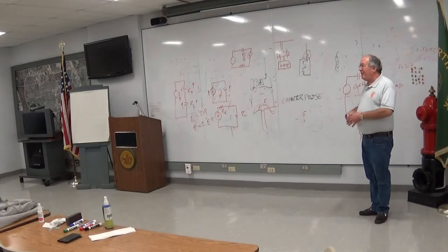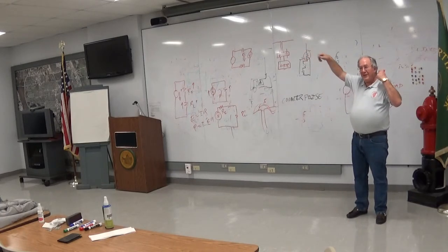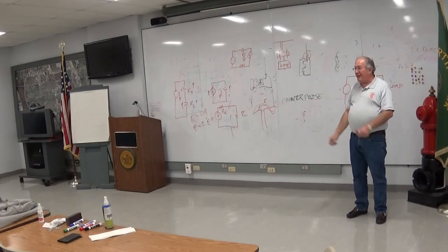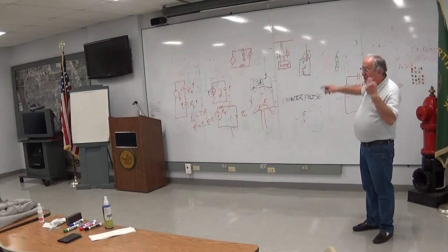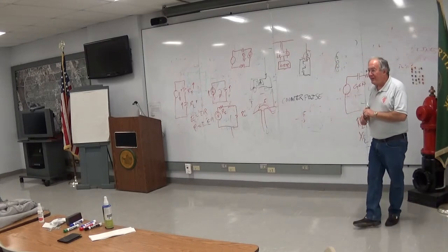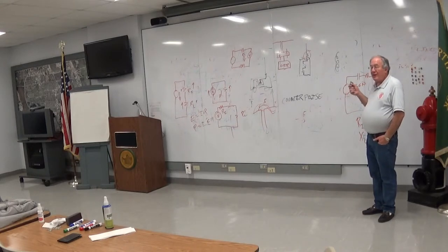You got a backyard that's X number of feet long, you just run a piece of wire there. And you feed it in the center, or you can even feed it on the end, and ground the other end, making it like a quarter wave radiating element instead of the half wave that you would prefer it to be. Works just fine. I won't say as well as a dipole will, but it does work.